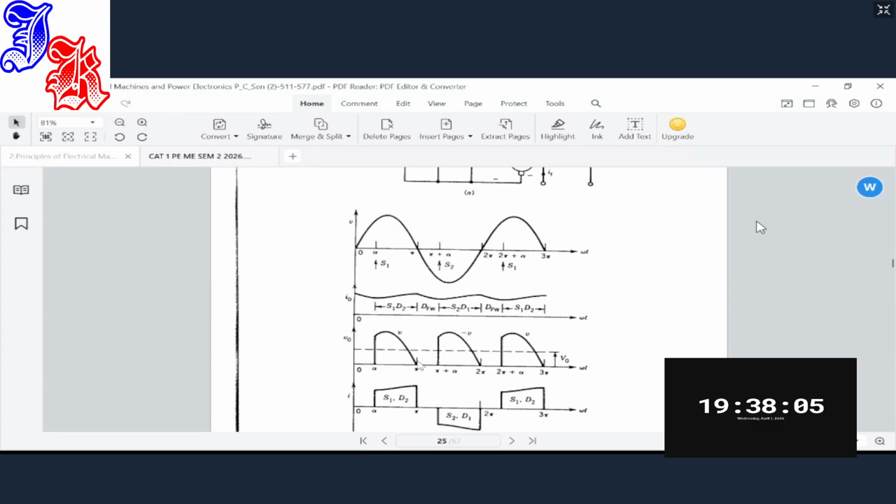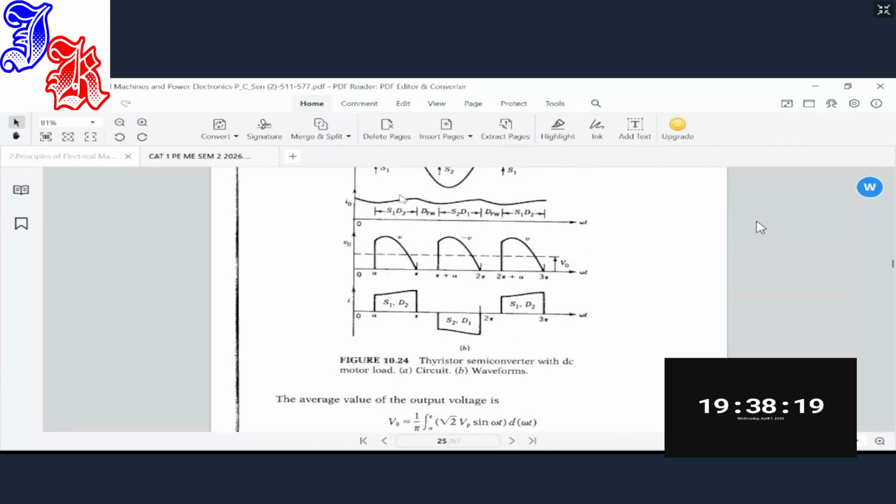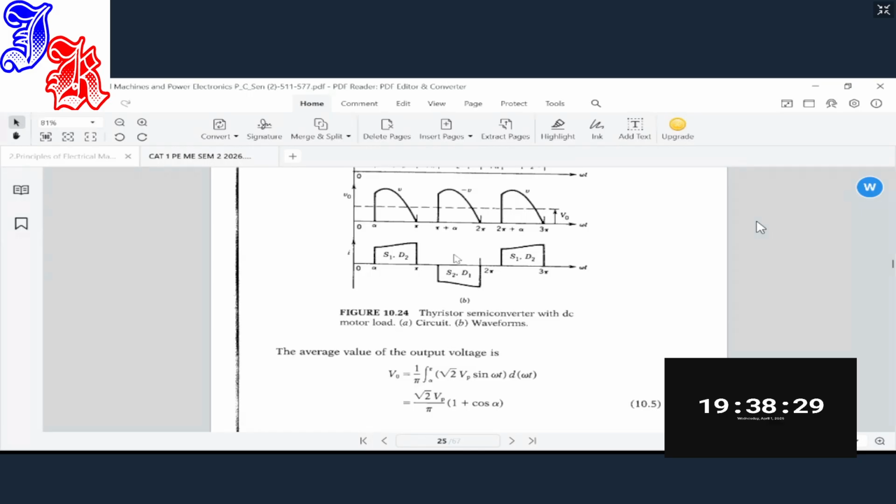And now you can see we don't have the negative voltage having to carry, or push, the current that was lagging, because we have already taken care of it through the freewheeling diode. So we are still able to attain almost a straight line. And for the output voltage, we have both the negative and the positive cycle forward biased through connection of both the resistors and the diode.